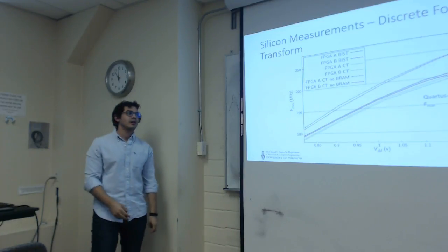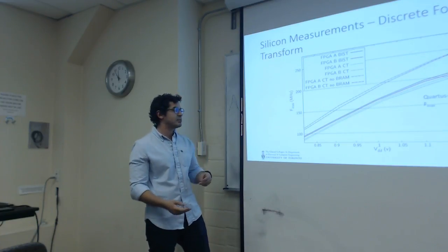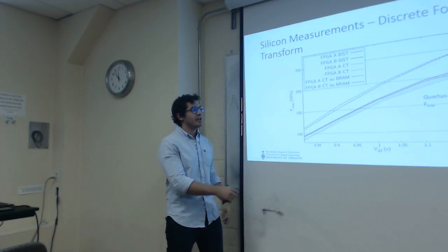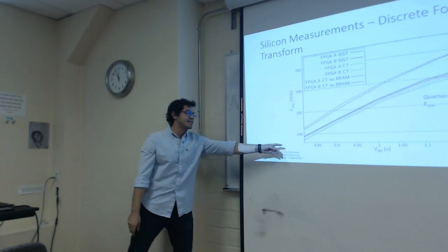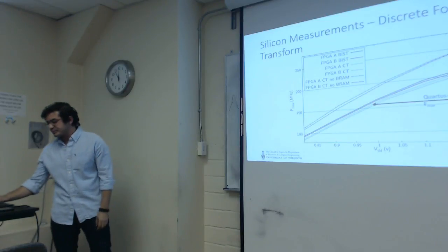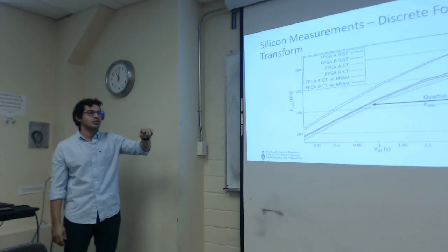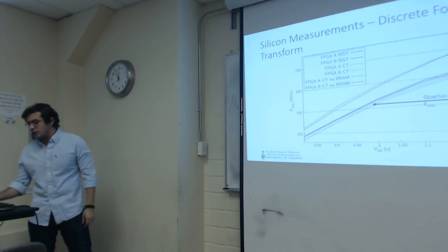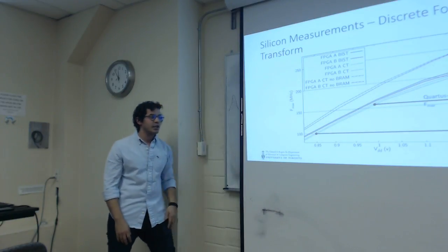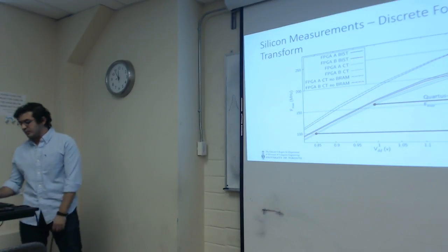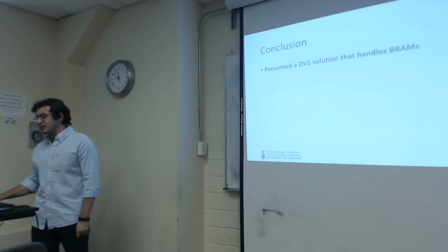Now with our new work, generating a calibration table that takes into account BRAMs, we're able to generate these two curves that show that, no, these are actually safe values to run your application at. If you want to run this application with no timing margin, you'd get around 32% power reduction. If you have some timing margin and you want to run the application at 100 megahertz, you'll get up to 46% power reduction.